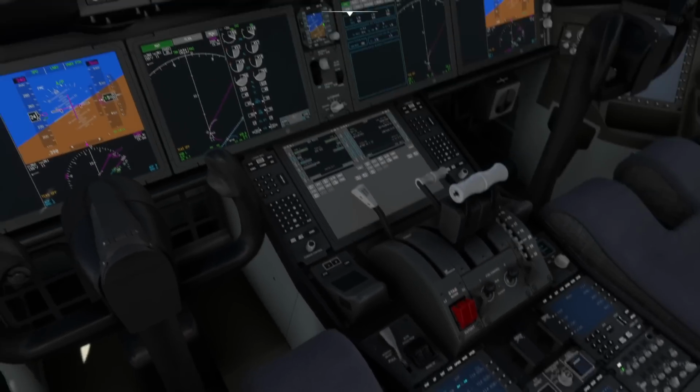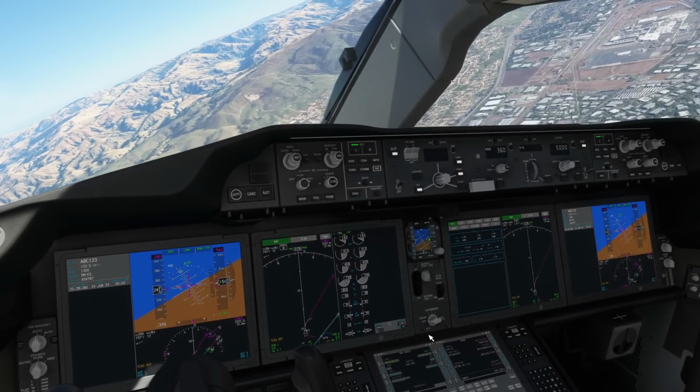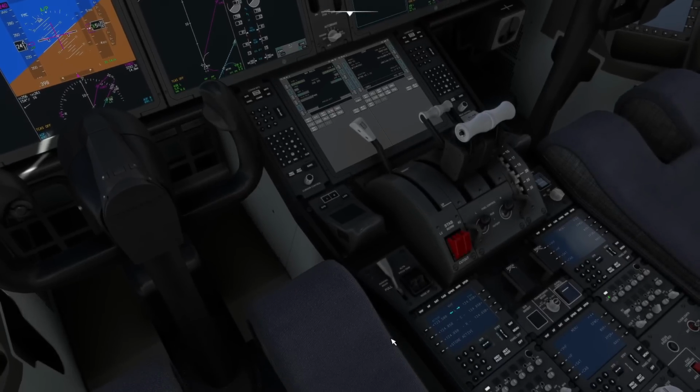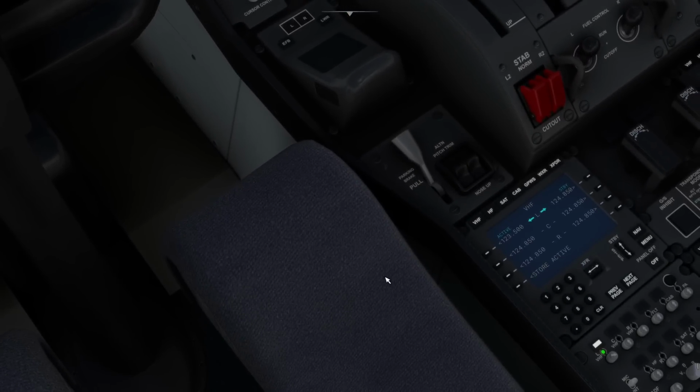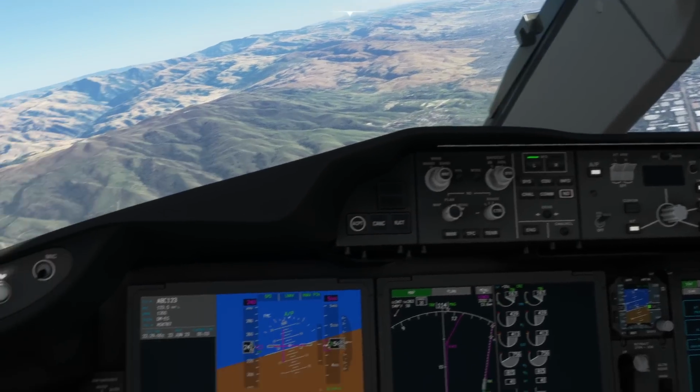I'll shut it up. So it just shows, doesn't it, the learning curve when you are not familiar with an aircraft, with just silly things like setting comm radio frequencies. So I had to go for a valid frequency to begin with. I keyed in an invalid frequency. And then I was able to put it into standby and then use the transfer button to transfer it over to the active frequency. So that's just familiarity with the buttons in the aircraft.